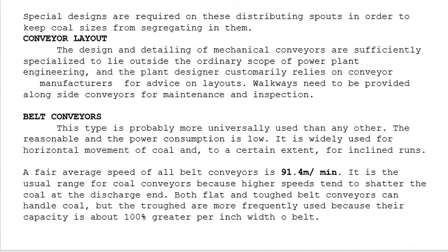So conveyor layout. The design and detailing of mechanical conveyors are sufficiently specialized to lie outside the ordinary scope of power plant engineering, and the plant designer customarily relies on conveyor manufacturers for advice on layouts. So walkways need to be provided alongside conveyors for maintenance and inspection.